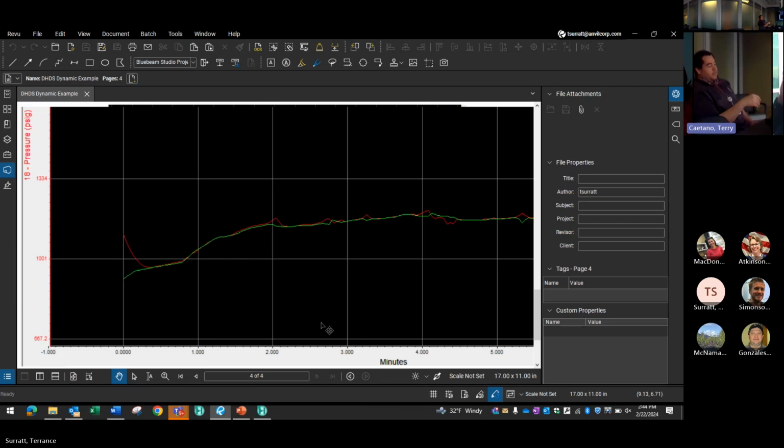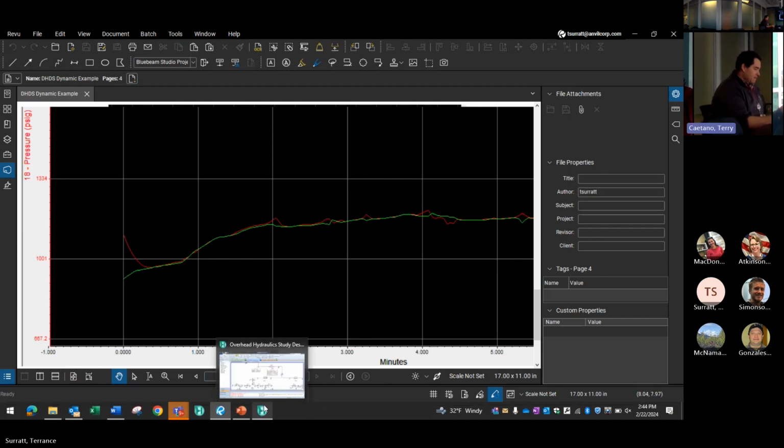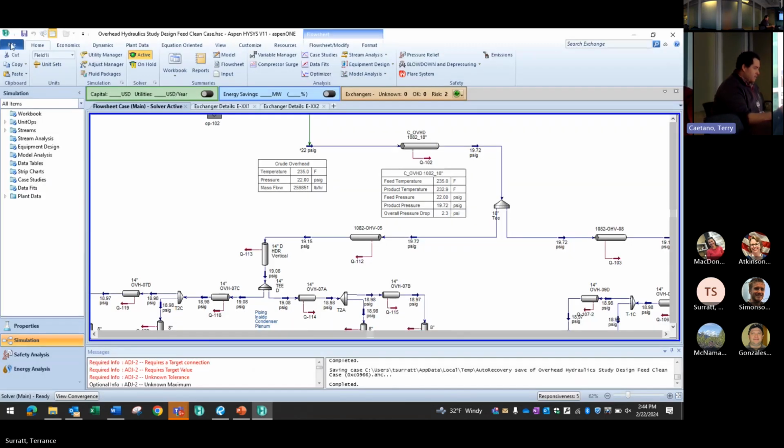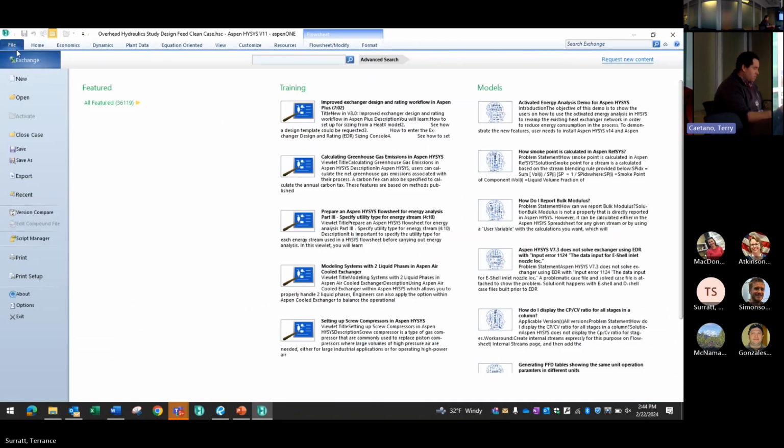And so this was looking at the settle out pressure at the lowest pressure piece of equipment in the system and just assessing if that settle out pressure would actually achieve overpressure or not, exceed the MAWP of the equipment. Then the last example I had, I just wanted to quickly run through.